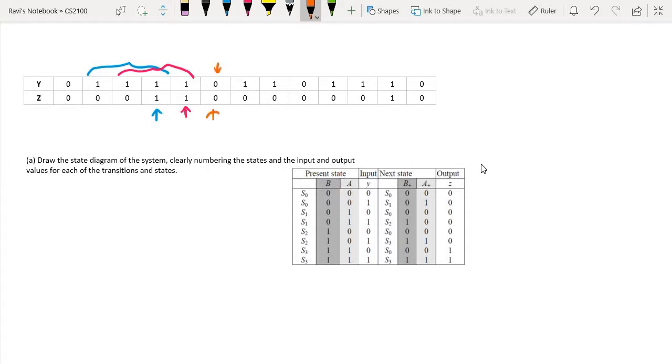Whenever it goes 1, I need to have three consecutive ones before the output can be a 1 again, like shown here. I think that part everybody is clear. And the state transition diagram that I've shown you is one with 4 states, and some of you have come up with a different approach with 3 states, which is also possible. I will not go through all the possible combinations, but as long as you understand the thinking process, I think that is what is important.